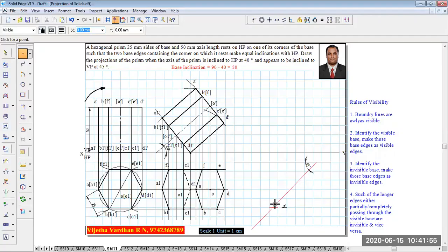Okay. Once we have drawn a point over there, what we are supposed to do next is, using the compass, measure the distance between O1 and O. Now, with O1 as the center, without changing the radius, draw a construction arc over here and locate a point if necessary. Then, using your pencil, name this corner O1 and this corner O.